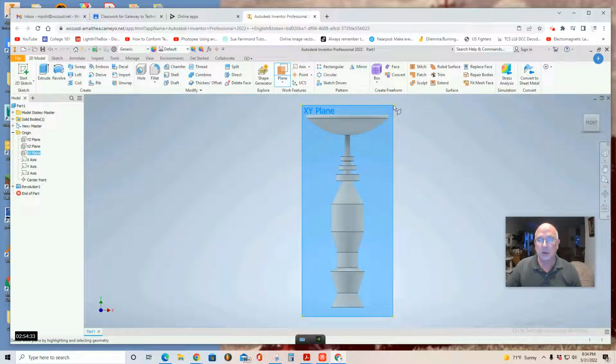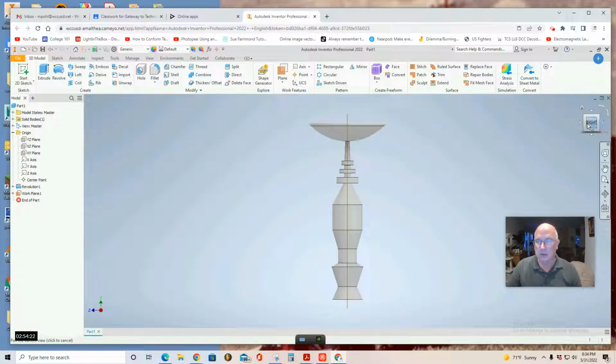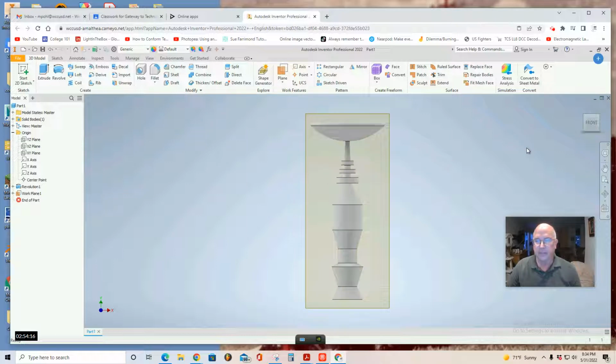and then I'm going to grab this yellow handle. With my left mouse button, I'm going to click and push until I see a 0, and then I'm going to hit the check. You can just verify that that goes right through, and then it's slicing right through my probe. I'm going to return it to the front view and start a 2D sketch on this perimeter line.